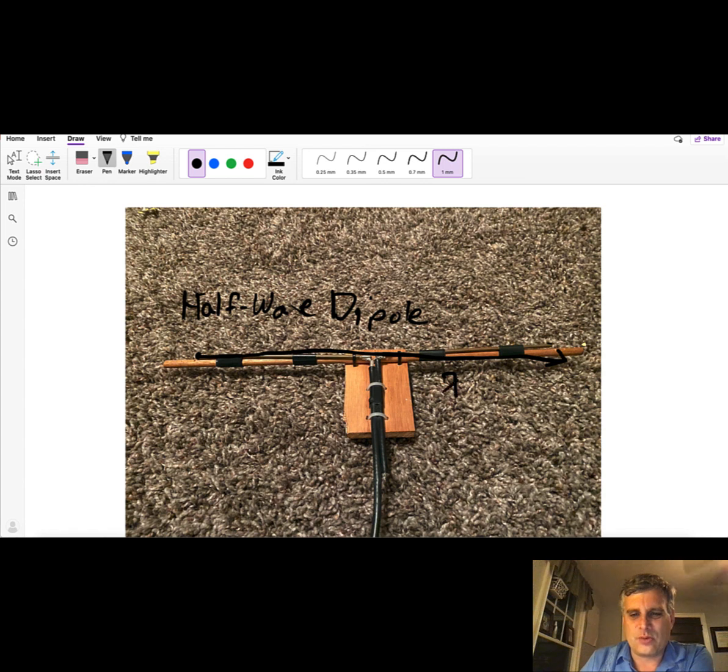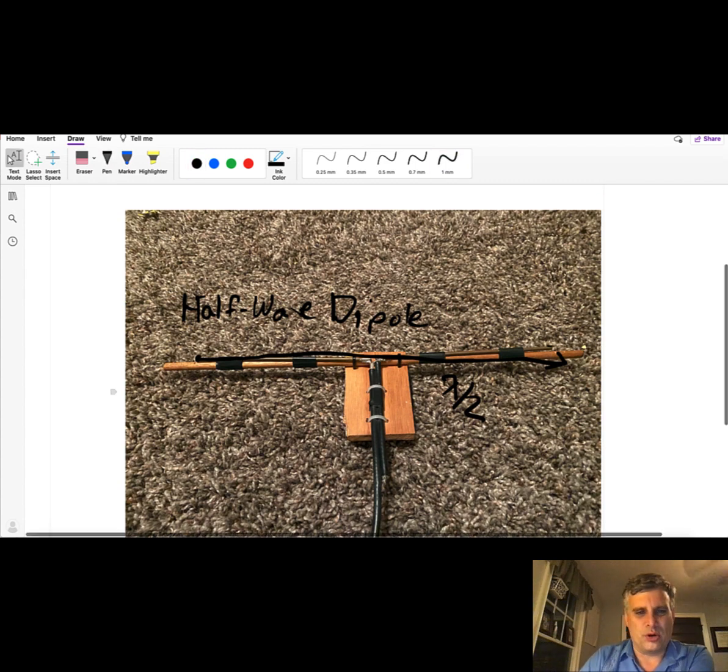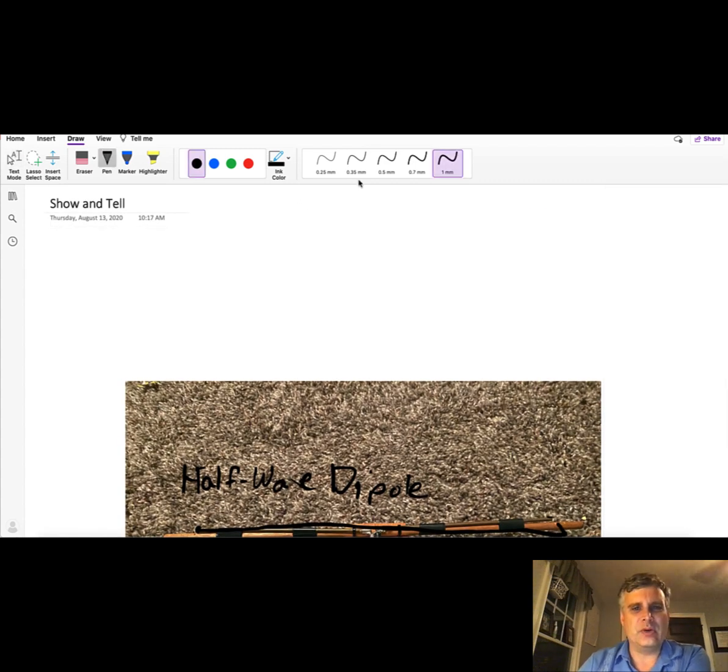That length is 1/2 of the resonant wavelength of frequency. Now, one of the most important equations in the class we know is this equation right here, speed of light or velocity of propagation. Usually for antenna engineering, our speed of light is our velocity of propagation because our antennas are in free space or air. We know that that's equal to lambda times the frequency.